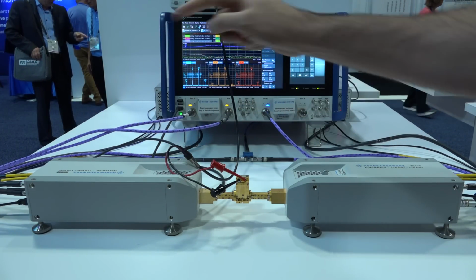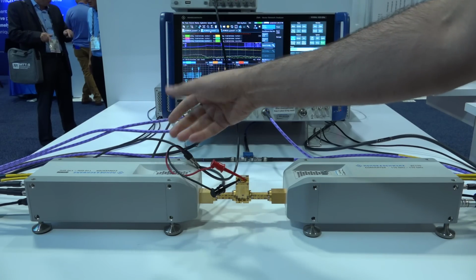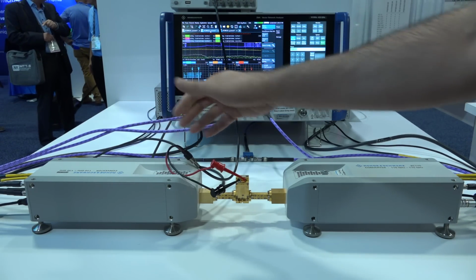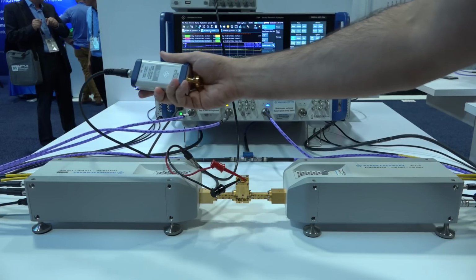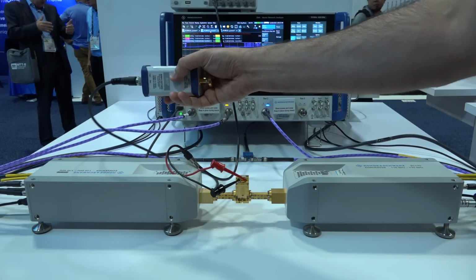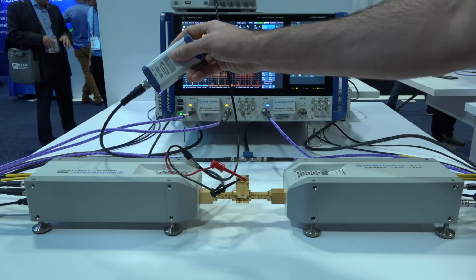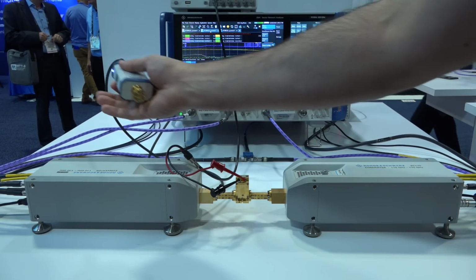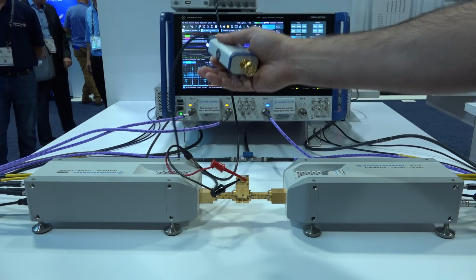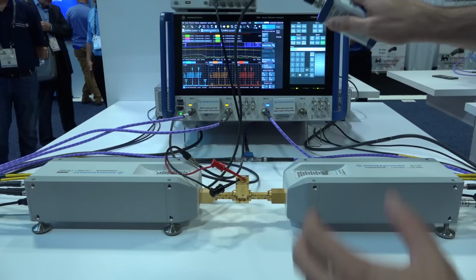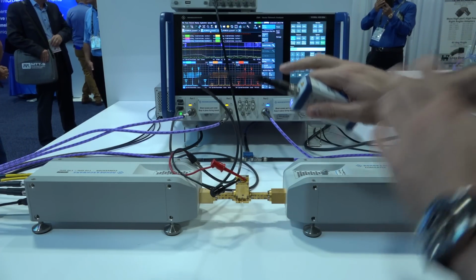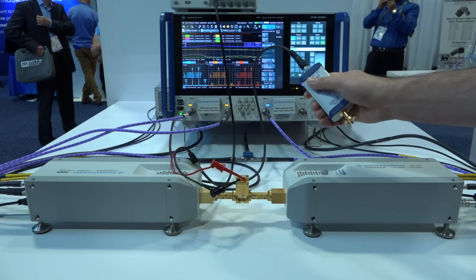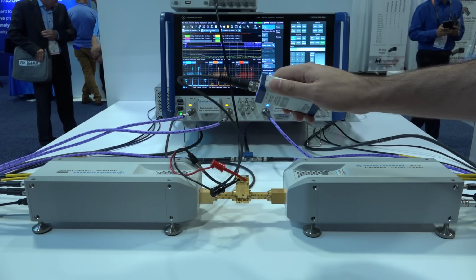Now at the same time, because you want to measure nonlinearity, things like compression, you would need to do a power cal, and doing a power cal at 110 to 170 is quite difficult, and of course we're going to do that with the new NRP sensor, which you've seen me show also on the channel, a thermal detector, extremely fast, allowing you to power cal across a wide range of output frequencies and powers directly on the units themselves. So you do a power cal, you connect it up, and then in one station with the ZNA, you can do everything at D-band that you could do below 40 gigahertz, which is crazy to think about, that you could do all those measurements in exactly the same setup.